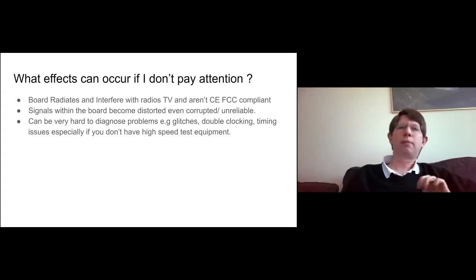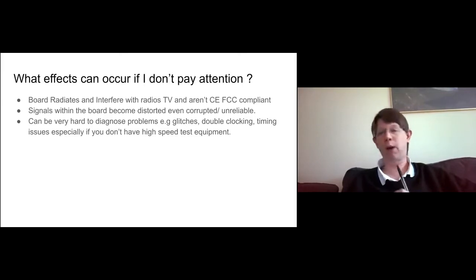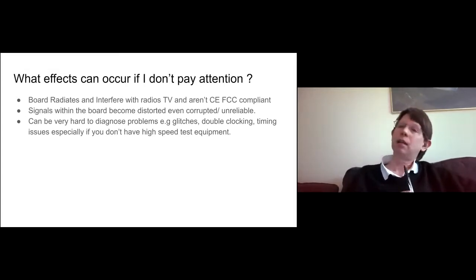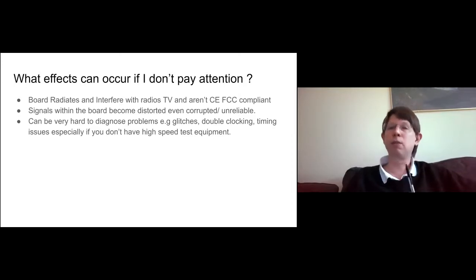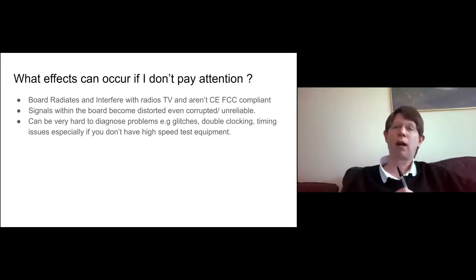So what can happen if you don't pay attention to your board? Well, the biggest thing that can happen is it just radiates and interferes with radios and TVs. With the old BBC Micro, if you have a radio near it and you tune it to the right frequency, you can hear your computer in the radio spectrum. Now, you might not worry about this, but maybe your next door neighbor might worry about it. Officially, you probably ought to start thinking about CE and FCC compliance, though I'm not going to talk about any regulations because that all becomes quite complex.